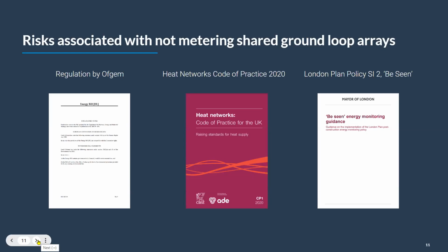It says, in relation to capturing data from a heat network, that furthermore, the AMR system should be able to record, transmit, and store the following information at least on a half-hourly basis: meter read, flow rate, flow temperature, return temperature, instantaneous power. So that's in Annex C, which states what ultimately you should be looking at when you're capturing data from a heat network, getting those performance metrics.